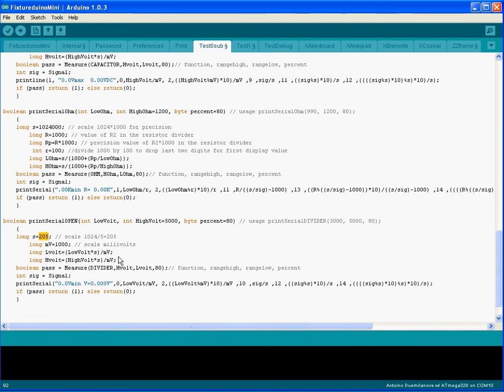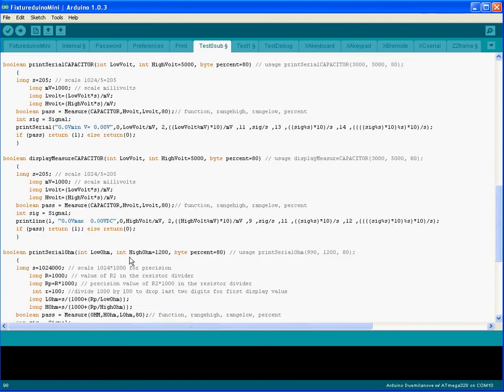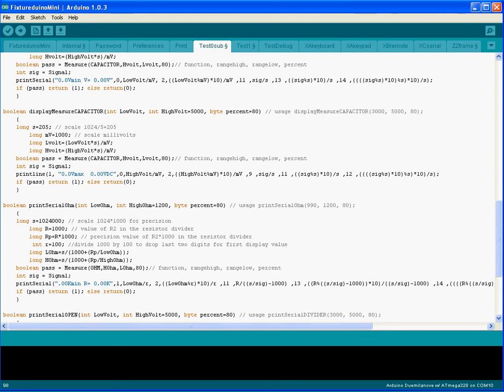So it converts that to the proper values based on these, and then sends it out to the print measure, and then it converts it, which takes those digital values and gives you a pass-fail, and then it measures the signal back and converts it to print it out here on the last line of the LCD display. That's how all these subroutines work.